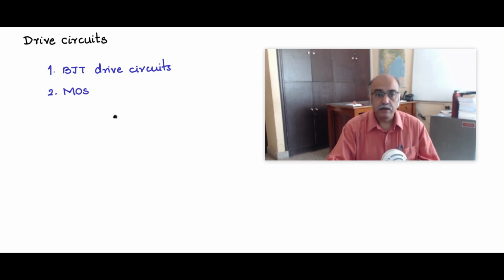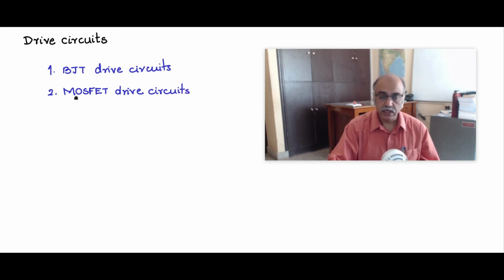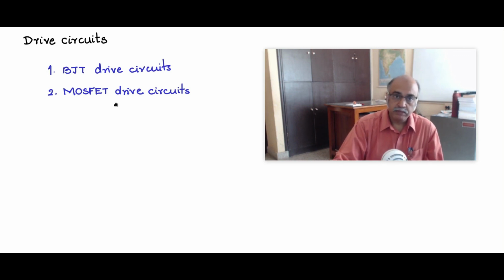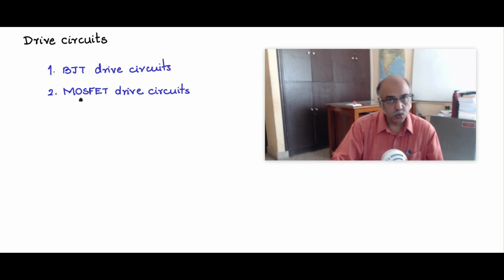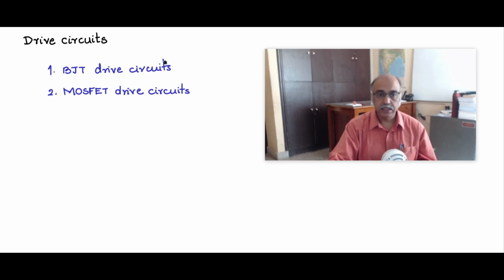The second one that we will be studying is the MOSFET. The MOSFET switches are very popular in all DC-DC converter circuits, and we need to study that. Of course, in high power and high voltage circuits, IGBTs are the most popular, but they have drives similar to MOSFETs, and if you know how to do the drive circuits for MOSFETs, you could as well do it for IGBTs too. So this is basically the focus of our discussion in this coming session, and that is what we will be talking about: drive circuits for BJTs and MOSFETs.